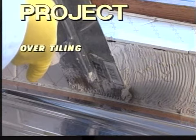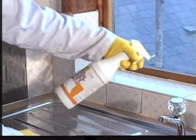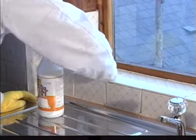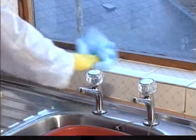Over-tiling. It's not necessary to strip old tiles off if you decide to revamp your kitchen or bathroom. Simply degrease the existing tiled surface using a good quality cleanser. Scrub with a small brush. And finally, wipe down.